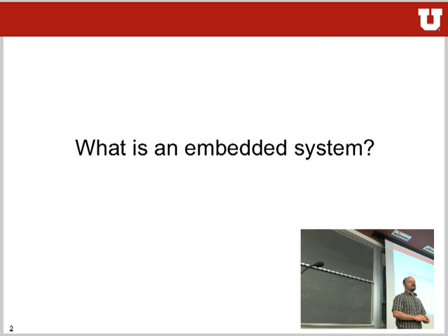All they have in them is a little bit of logic that just replies an ID back. But there are smarter RFID tags out there, especially active RFID tags, for example. They have logic in them, they have smartness in them, they actually do calculation and math inside of them so that they can do a lot more than just telling you a little ID. For example, some of them have flash memory in them that you can write into them with your RFID cards, and you can read that back out again. The key of RFIDs is that usually they don't have a battery, so you send them energy to run and do their execution, and then they will reply with a very short message back. So they have a very specific purpose. So yes, you can count them as embedded systems.